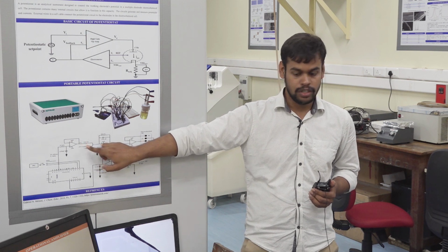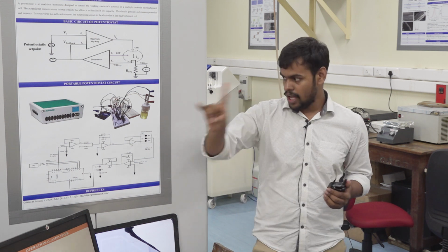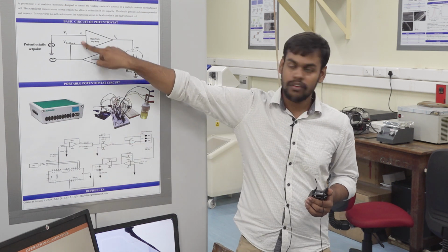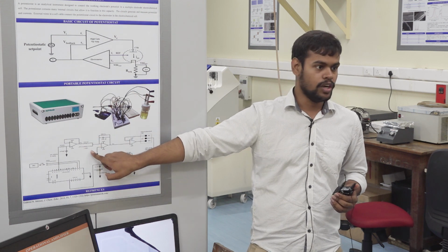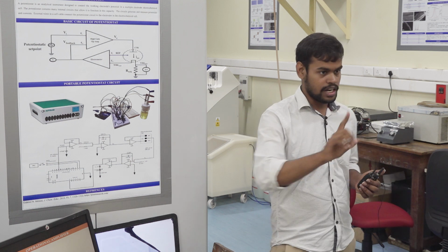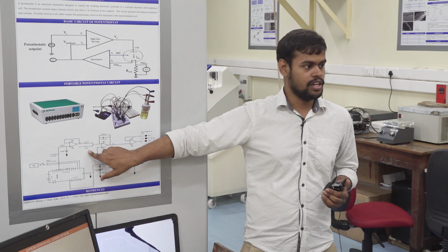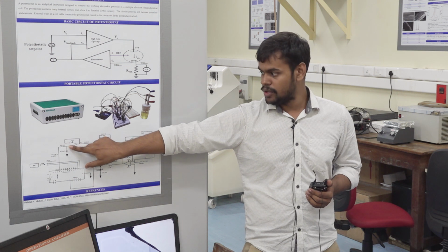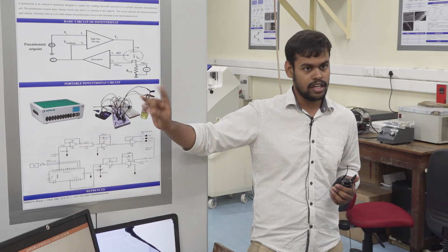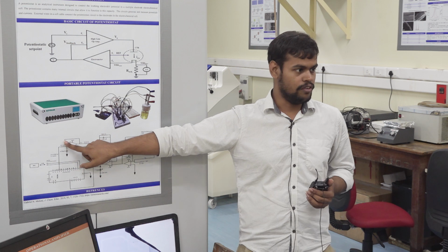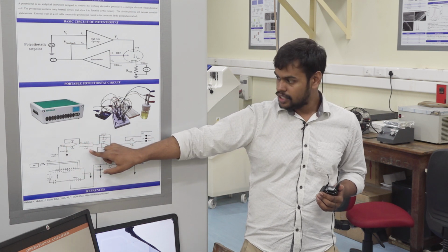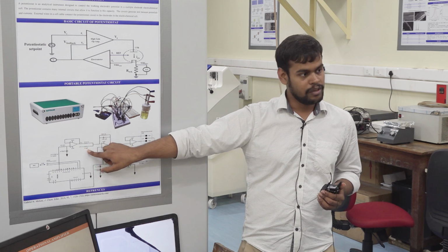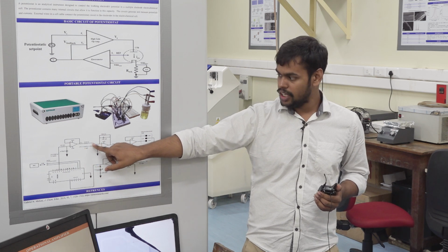There is a 510 ohm resistor. Now, it's a negative voltage regulator. Why am I using a minus 5 volt? I have a feedback kind of stuff involved here. This is a minus 5 volt divided by 1 kilo ohm. It will give a certain current. That's why I used a high ohm resistor here, not here. Let's just say the input gave minus 1.5. Minus 1.5 came here, divided by 510. Then there is a minus 5 divided by 1 kilo ohm. It will be the input at this point.